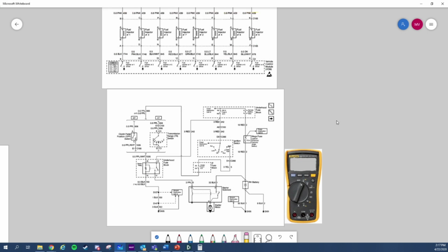Because I checked those. I checked for continuity. I checked for that, but did you move it around? Did you do the wiggle test? It beeps. But somewhere along the line, actually, I had taken off the clips, the connectors,